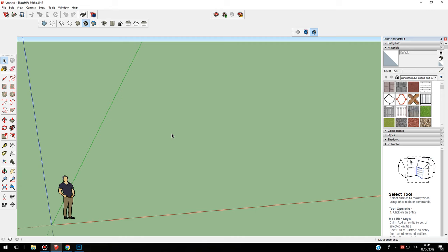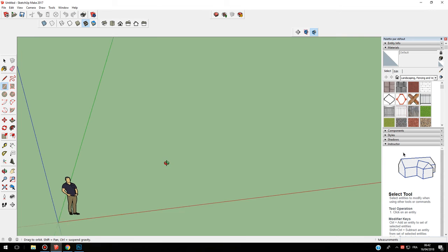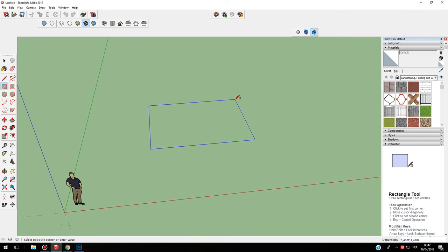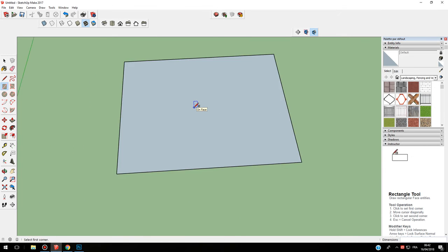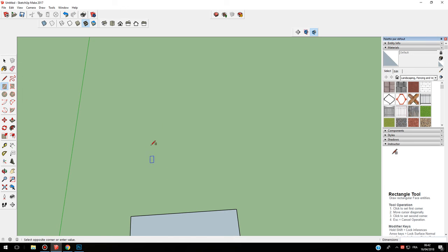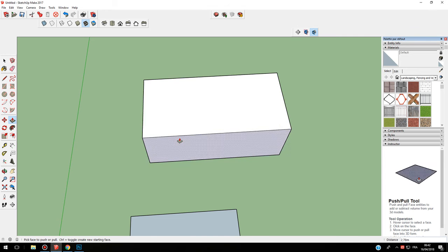Guides were called construction geometry because that's basically what they are, a special kind of entity that you create when and where you need them. So we are going to create a shape, a rectangle here, and a second rectangle here, and I push-pull my rectangle like this.